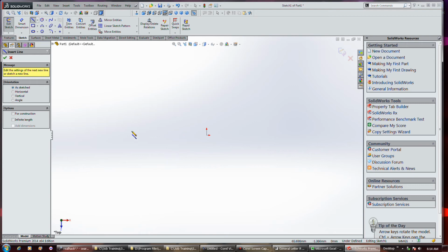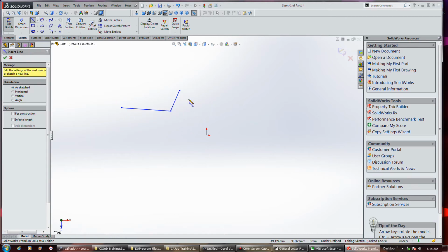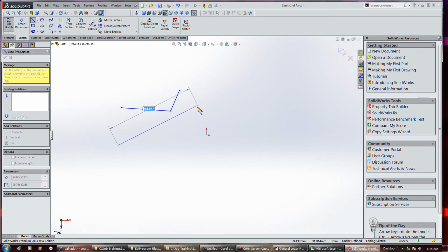Okay, I'm going to very quickly tour through some of the different objects here that you can draw in sketch mode. Firstly, with a line, you can click on a line and draw like that. If you double click, it stops the line. Okay. If you click and drag, it'll draw a line from the point you click, and it'll only draw a single segment.